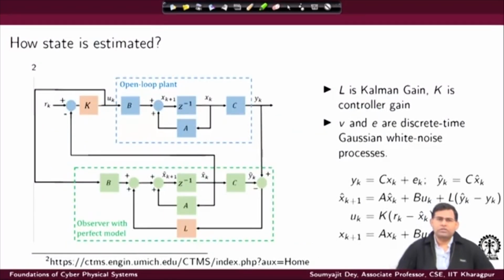So, in general, how is state estimated and how are such state estimates put into practice? So, typically that is how the control works. Suppose let us assume that you have indeed designed such a Kalman gain or a Kalman estimator, okay, and your original controller has some gain k. Okay. So, typically this is how you put it into practice. You will have the open loop plant. So, this is your plant. You can see that this is in the form of Ax plus Bu, right. Xk plus 1, the update is happening based on Ax plus Bu here, right,